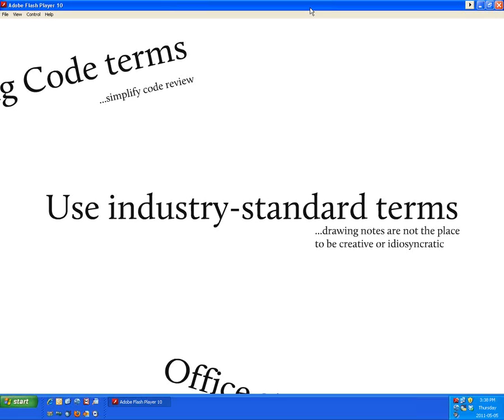One of the things that I encourage our folks to do is to distinguish between cold form metal framing, which can be abbreviated CFMF, as an industry standard term for the structural steel studs that are specified in Division 5, as opposed to the non-structural stud framing that's specified in Division 9.